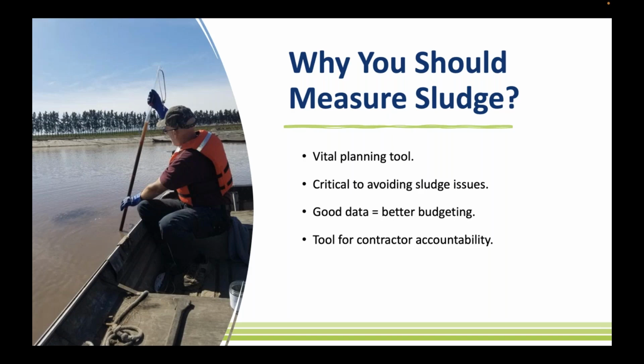So super important. And then when you do that contract, and you do have the contractor come out and remove that sludge, you need to know what was in there before, and then you need to go and measure what was there after to make sure that you actually removed sludge. Because I can't tell you the number of times that I have heard from a customer, hey, we removed sludge 2 years ago. We do a sludge survey, they still got 2 feet, right? And we'll talk a little bit more about that next week as to how that occurs, why that happens, and how frustrating that is. But you need to know. And then if you know, you can hold them accountable to removing X amount of cubic feet, and it's pretty simple and not too hard to do.